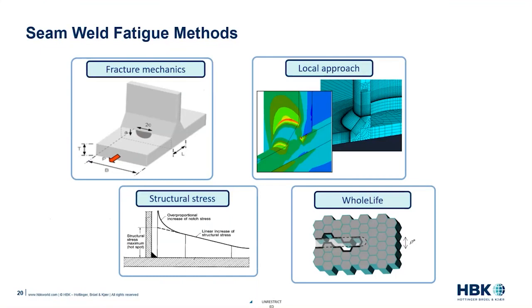Or a local approach, where these attempt to predict the stress or strain at a localized crack initiation site in the weld.